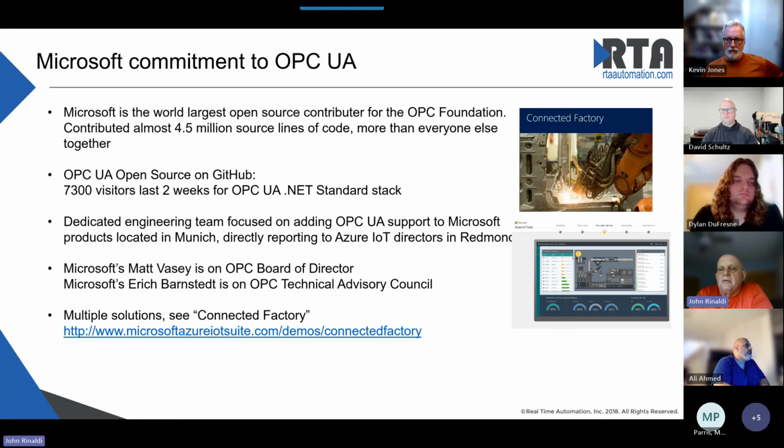But I really don't have a handle on how much OPC is really being used in the US. I know in Germany it's all over the place, but not so much here, because Allen-Bradley hasn't really been rushing to support OPC, though now they've committed to putting a server in their Logix PLCs at some point in the future.